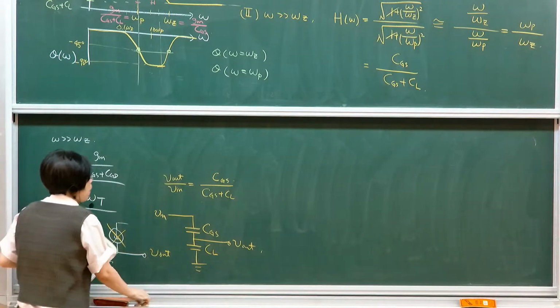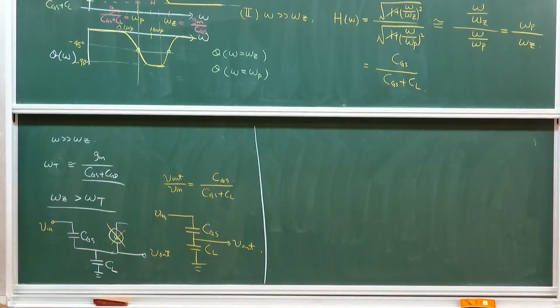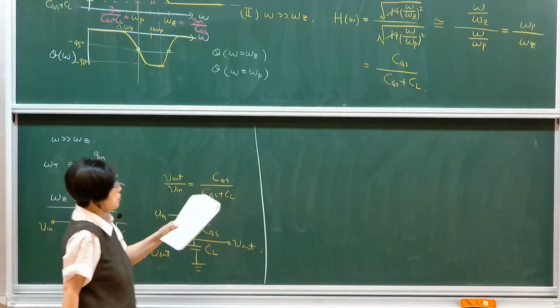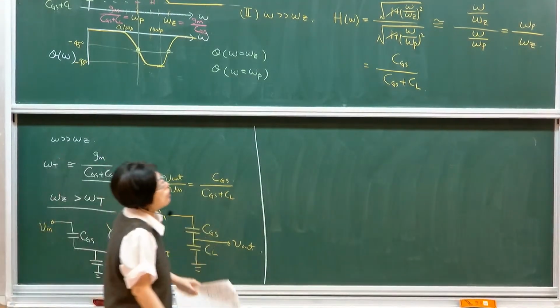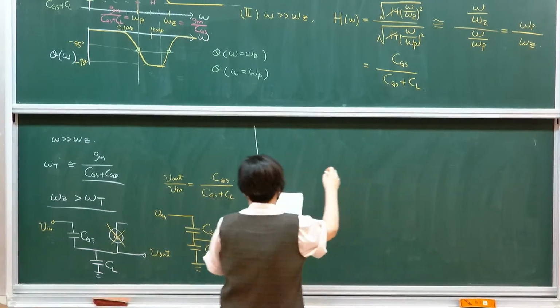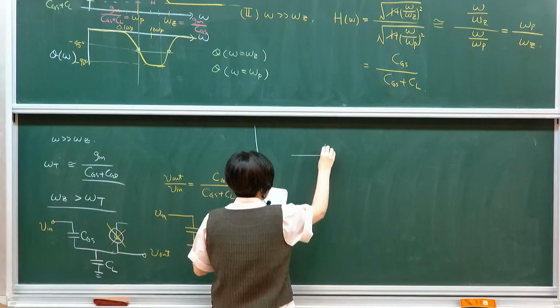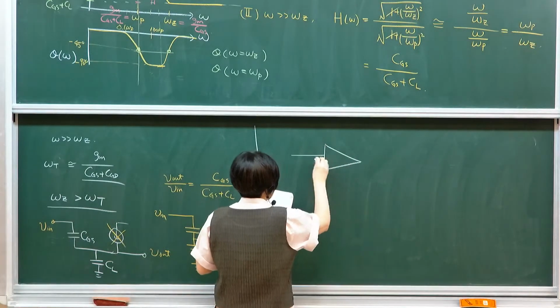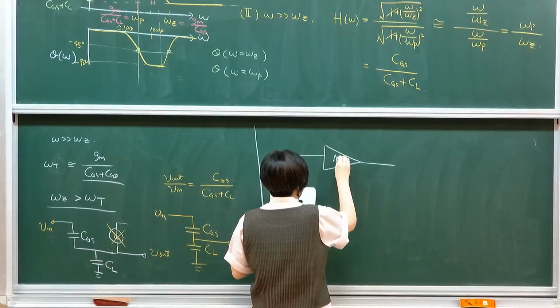Okay? So we already tackled the first part. Let's look at its input and output impedance. As I said, if you look at the Miller capacitance effect in this particular circuit, remember this is minus A1.